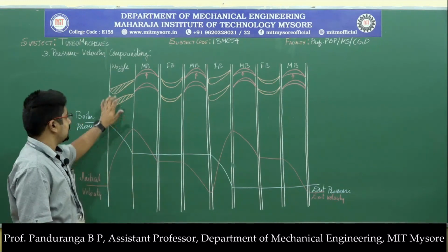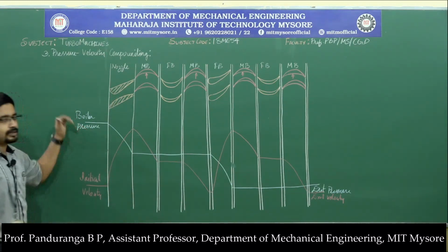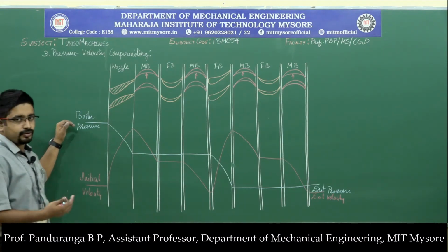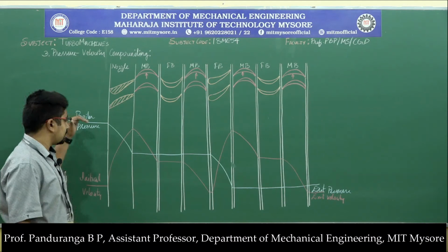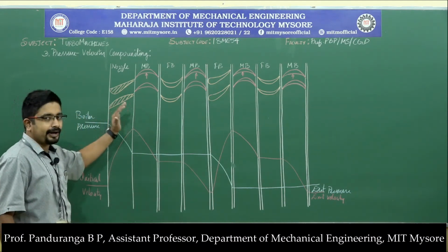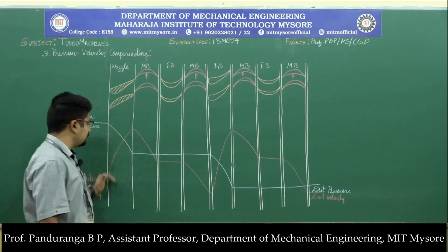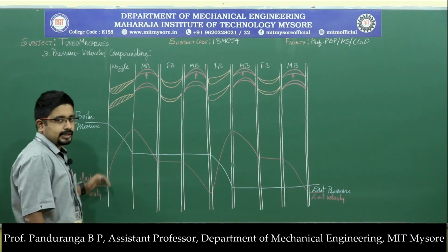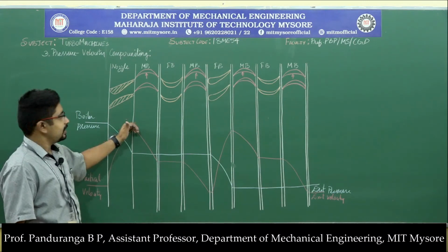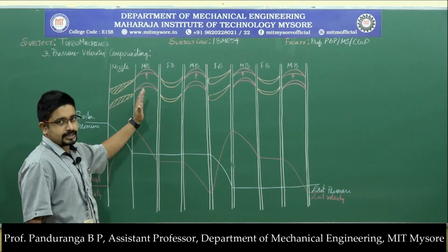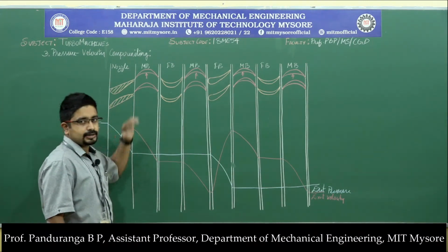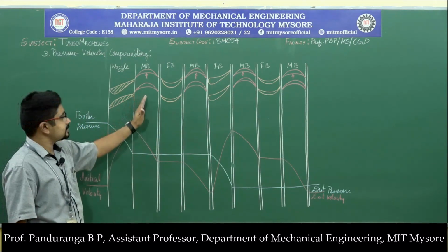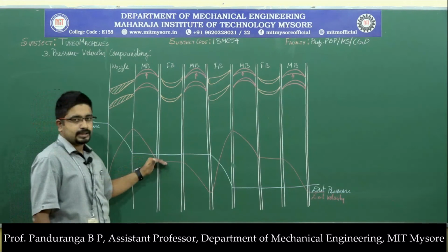So once again, here the steam enters the nozzle at the boiler pressure, which is very high, around 250 to 300 bar, and here in the nozzle a part of the pressure energy will be converted into kinetic energy. So the pressure partially reduces and the velocity increases, and as the steam passes through the moving blade, a part of the kinetic energy will be absorbed, but since the blades are symmetric, the pressure remains constant.